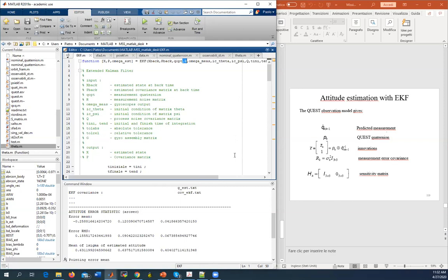So for each measurement, for each star, you have an associated sigma that is related to the star catalog, so a delta in V, and an error delta W that is an error in the sensor, for example a misinterpretation of pixels or a magnitude error, as we have seen during the course. But I can show you in the code, that would be clear.